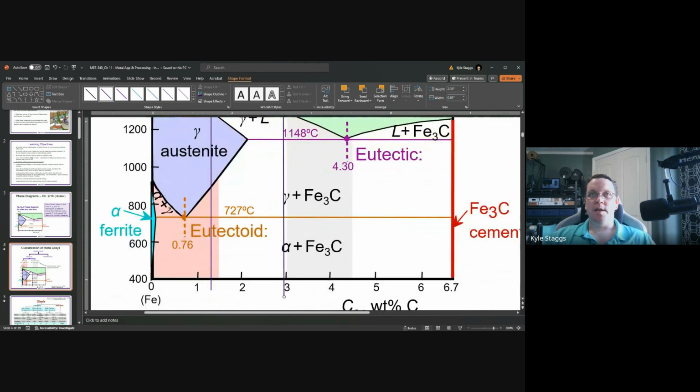Ferrite only is just this very narrow little sliver of a region. So unless you have virtually pure iron, you're almost never even going to see this region at all. The zone is there, but that's why it's very hard to analyze things like inside this alpha plus gamma window. So this is only austenite and ferrite. As you continue to cool down, you're going to end up with only ferrite and some amount of cementite, probably in the form of some kind of pearlite with a lot of the concentrations that we're using.